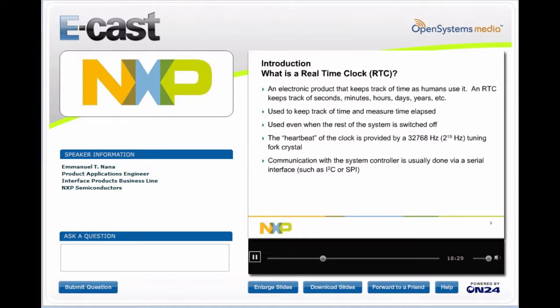And then to continue with the presentation and looking at the low power devices within our portfolio, now I want to talk about the low power accurate real-time clock. These are the PCF2127A and the PCF2129A. Both devices have a TCXO integrated within the device.